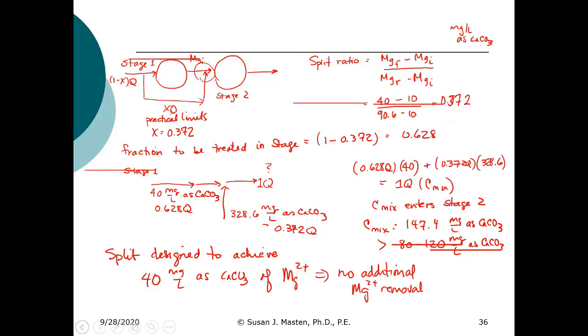That's based on experience, knowing that at about 40 milligrams per liter, the water isn't going to taste metallic, and isn't going to scale or produce significant scale in the distribution system and in your water heater. So that's where that 40 comes from.